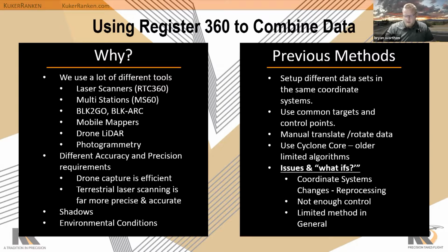These will be the LAS, LAZ files that you get from photogrammetry from Pix4D, from your SLAM scanners, BLK2GO, mobile mapping, your Pegasus TRK systems. Those are unstructured, and they don't have the same amount of metadata. Traditional terrestrial scanning has more metadata going on in the background, and we have all these tools, and we have to have a way to combine them, right?